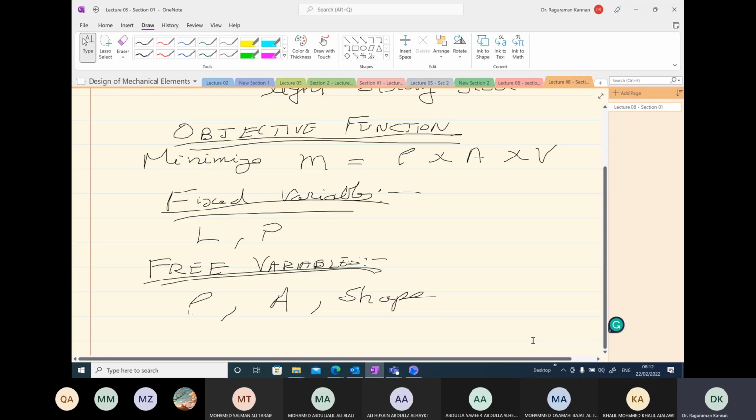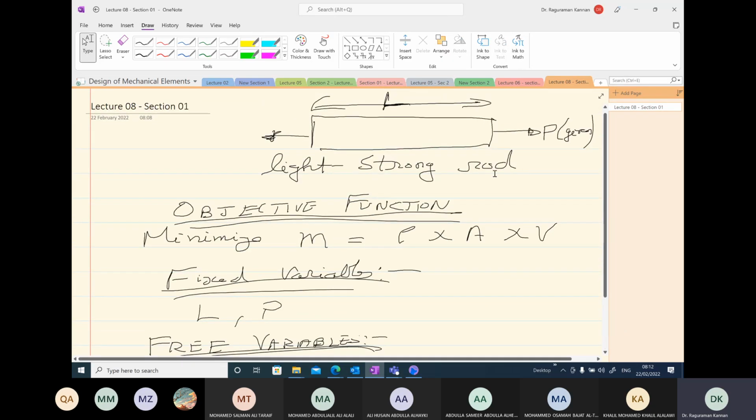So leaving this, now what is our aim? What other quantities are given? We are given a strong rod, so something about the strength is given. So let's assume here we are given yield strength, for example, Sy. So this is the strength parameter we are given. So we also have to input the strength parameter here as a fixed or minimum value, so it should be greater than or equal to this value.